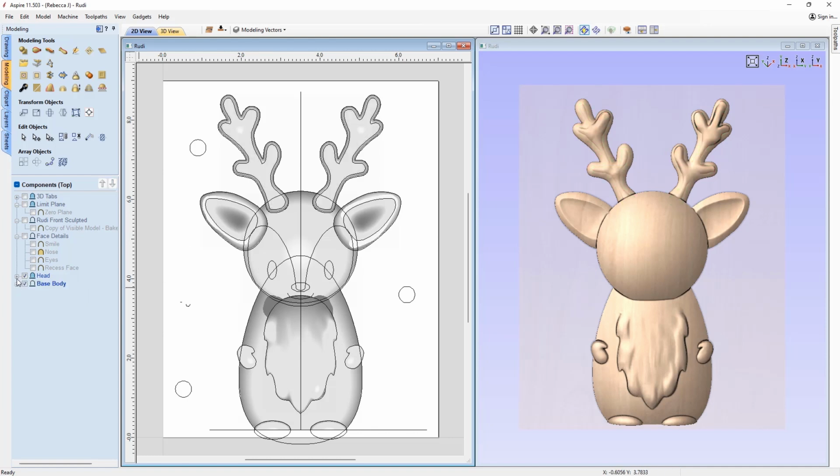Okay, so let's just minimize that. Then with details, here I've got this shape which creates a real nice negative shape which forms the bridge for the actual nose here. Got eyes and nose. The mouth was the only exception here where we didn't use the create shape tool. We actually used the extrude tool. So I used this rail with these two cross sections. It started off with a flat shape, so it's coming in at 0 and it blends into this subtracted shape to get that recess, and then it blends back into a negative shape as you can see over there.